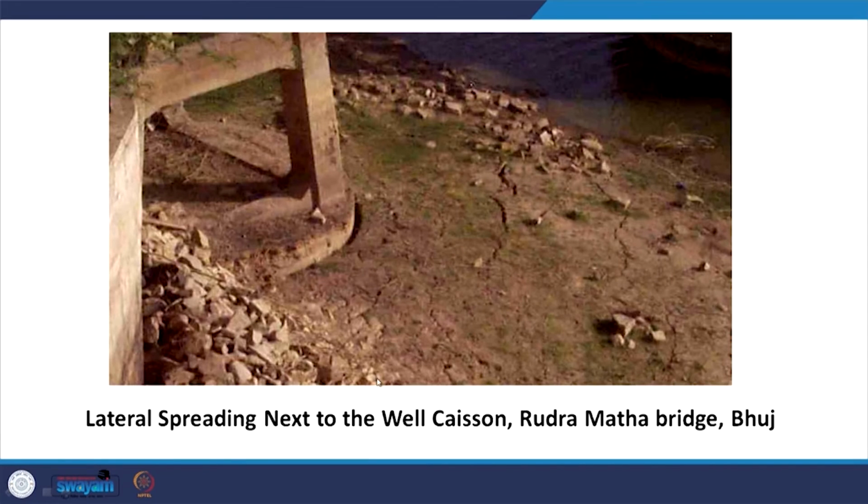In this slide you can see there is a well here, and there is lateral spreading occurring here. It is due to liquefaction-induced lateral spreading, because the soil here got liquefied, and as a result there is spreading. This spreading tried to subside this well foundation, but the well foundation was properly designed and it could easily survive.